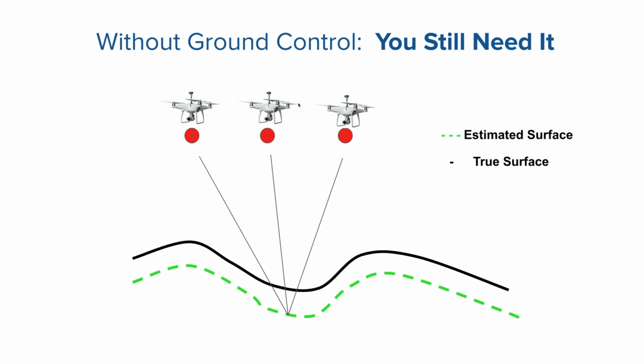horizontally, remember what we mentioned, the accuracy out of the box with an RTK capable drone on your ground control point targets or checkpoints, you're going to see that it's usually going to be plus or minus a couple centimeters. But what you'll often see, and we've had several people comment on this, is that, hey, if I'm not using any ground control points, even though my horizontal accuracy is very good, I can see a small vertical bias. And that bias might be anywhere from 10 centimeters up to half a meter, right?